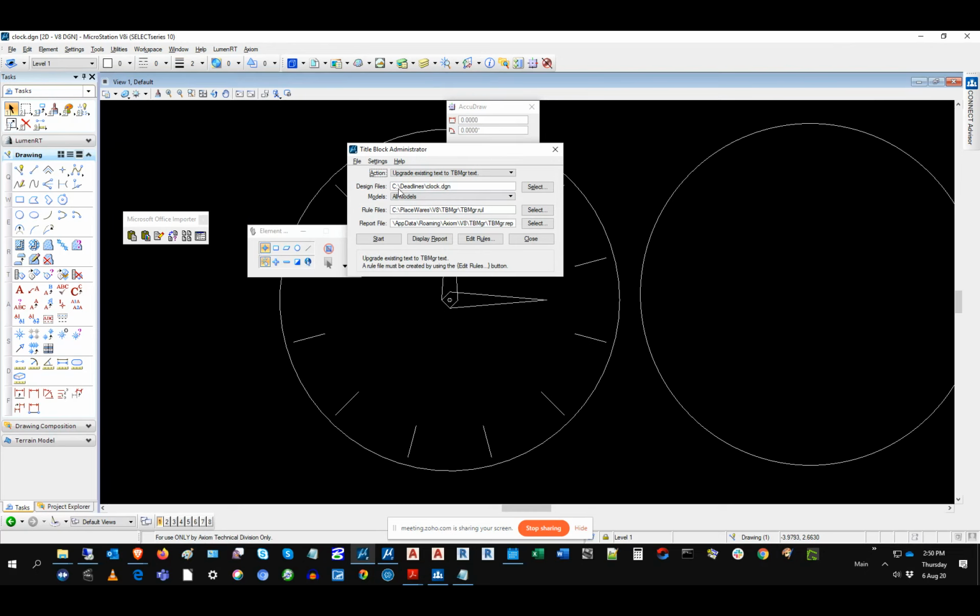And then once you do that and you run that process on those files, it'll recognize that text, so you can do what I explained earlier, which is grab copies of that data from your design files, your sheet numbers, sheet totals, that sort of thing, where you can then increment them or update data of your sheet numbers and sheet totals in the database, whether it's a spreadsheet or Microsoft Access database, and then push that updated data back to your design files.